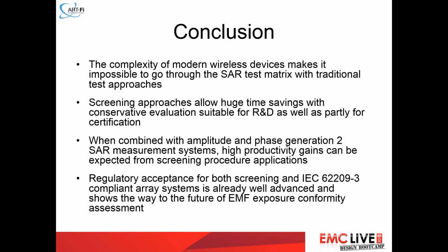When you measure SAR, first, the RF transmitter of the device is connected to the antenna, which is not 50 ohm the whole way across the band. And second, the device is coupled with the phantom on which you are testing it. So you're not testing on a 50 ohm load in the case of SAR. That's why there is not a perfect proportional relationship.